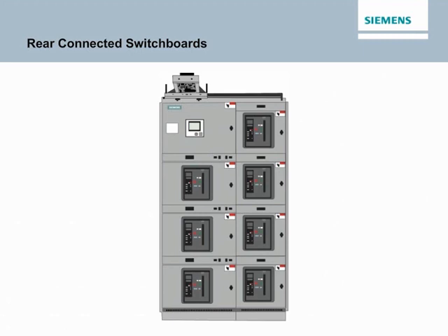RCS switchboards accommodate systems up to 6,000 amps, 600 volts maximum in any 3-phase, 3-wire, or 3-phase, 4-wire configuration. The main bus can be specified for 600 to 6,000 amp rating. RCS switchboards use WL insulated case UL489 or LV Power UL1066 circuit breakers with draw-out mountings and continuous current ratings from 400 to 5,000 amps for main and branch devices.